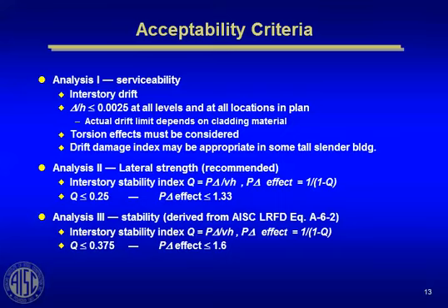Well, that might be okay if you're a traditionalist, I guess. But if we're ever gonna move forward in trying to more accurately predict deformations in our frames, we got to do a better job of modeling them. And we know that second order effects exist. The P delta concept is very well researched and documented, so we know it's there. So if we're really going to get meaningful drift checks, we need to do a meaningful model as best as we can, and we need to capture the properties of the frame as best we can.